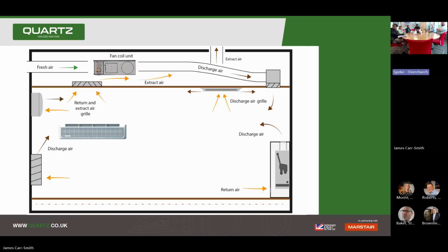Typically what you'd find on a wall-mounted unit is a typical DX split type unit, where you would have it on a rotating vane at the bottom. Those sorts of units won't make use of the Coanda effect. So this is specifically designed for that benefit.